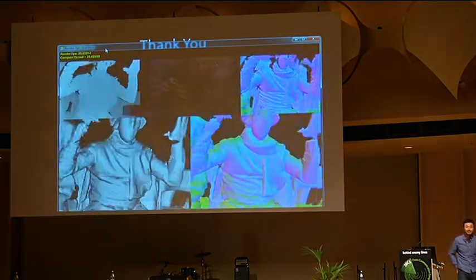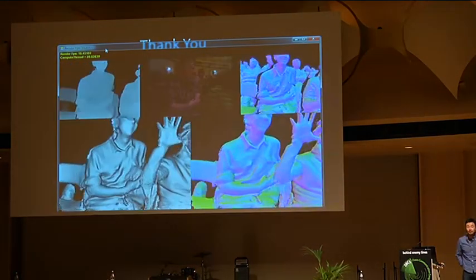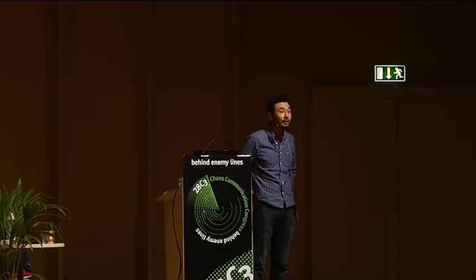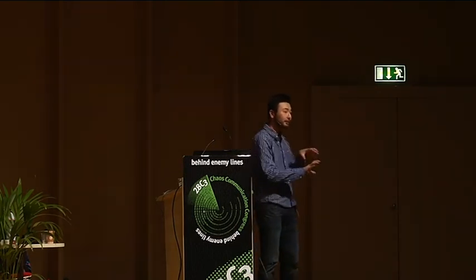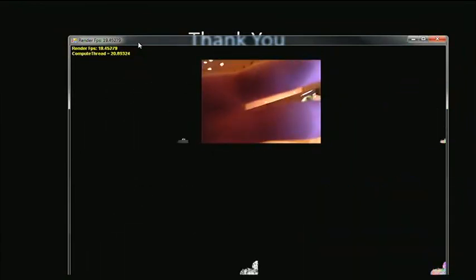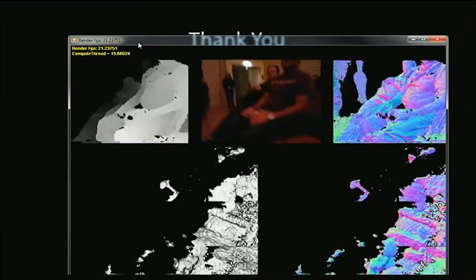Hello there. First of all, one really quick question. Do multiple Kinects interfere? Because you get multiple patterns thrown on the scene. Yeah, they do, because they produce so many dots in the scene, they can't actually figure it out. And I was wondering, have you thought about using multiple normal video images instead of the Kinect, calculating depth information from that? Because then you could do larger distances and you could do daylight. Yeah, we are currently working on it right now, actually. So using stereo cameras to feed the depth information into KinectFusion.